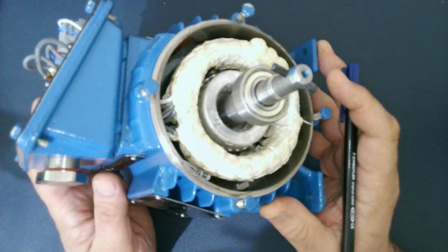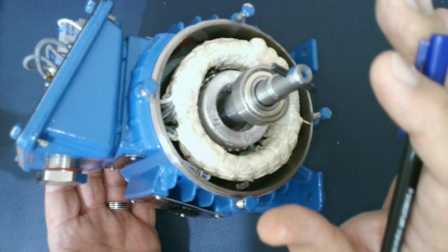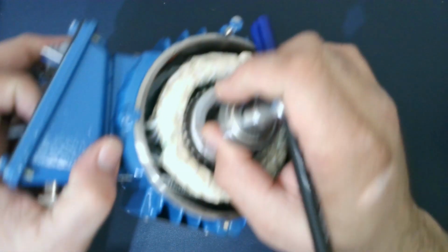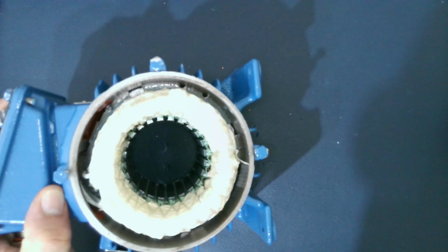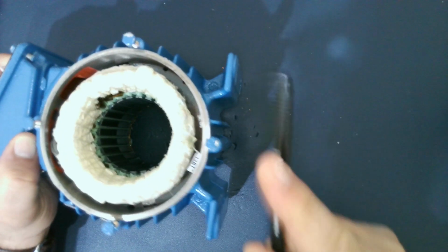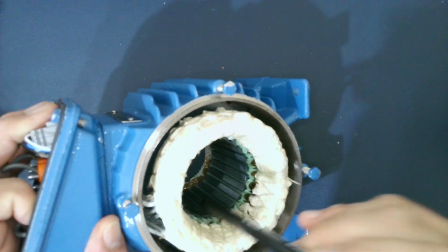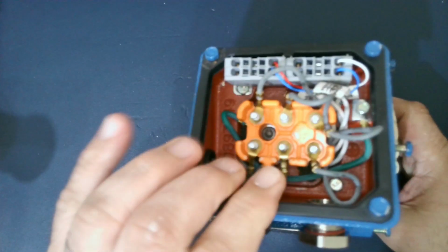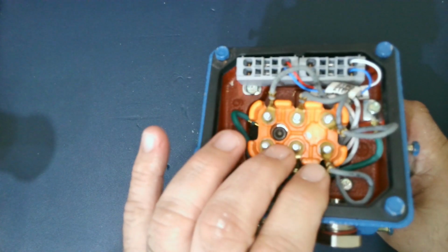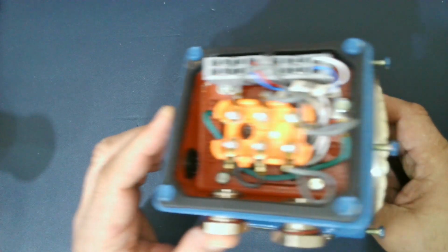Here we have another machine similar to the one I showed to you before, but I removed the end cover from both sides. So we are going to take the rotor away now. So we'll put the rotor away. I'm going to return to this rotor later on. As we can see here, the stator consists of slots and teeth, and these slots are furnished by 3-phase winding. So we have here in the terminal box 6 terminals for the phases A, B, C. We're going to return to this terminal box later.